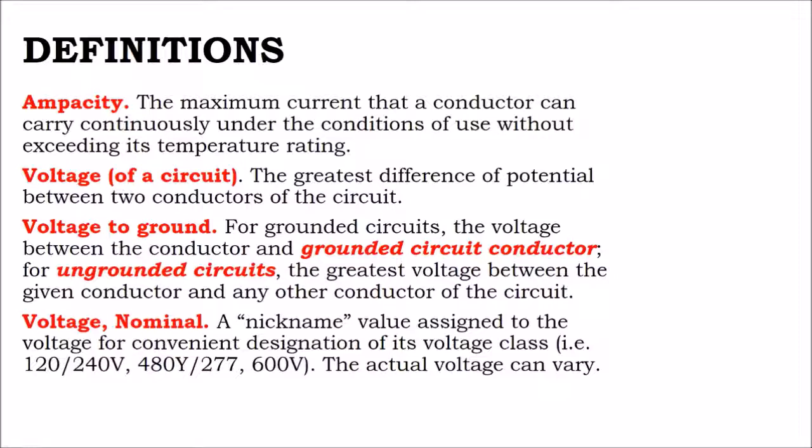Then you have a 48 volt battery bank, but for certain batteries like flooded lead acid batteries, you might have a maintenance feature where you drive the battery bank voltage up beyond 48 volts into the 50 or 55 volt range. The battery may be designed to take 60 volts, but its normal operating voltage is 48 volts, and that would be the nominal voltage. But generally, you don't design around the nominal voltage. Generally, you are designing around the maximum circuit voltage.